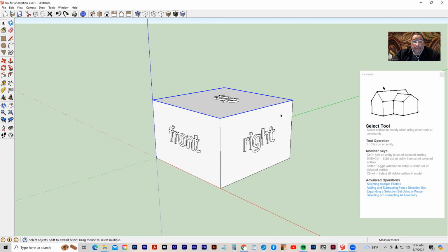And that's how you select objects in SketchUp. That's how you select. And I can trap select objects by dragging over them like so. And oftentimes what you'll do is you'll take a bunch of objects and you'll turn them into a group or a component so that you can manipulate them all together. And that's how I select the different parts of my shape with my standard selection tool.